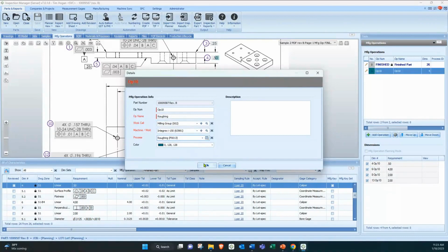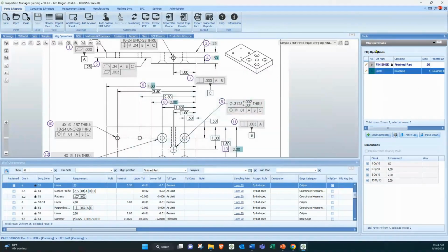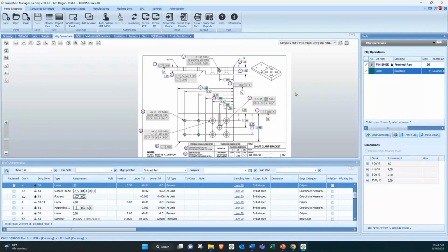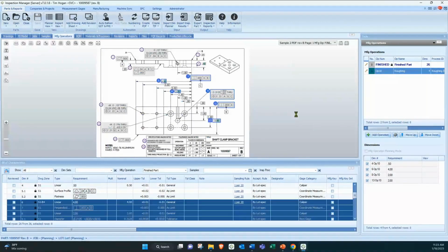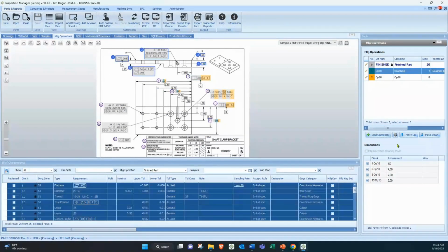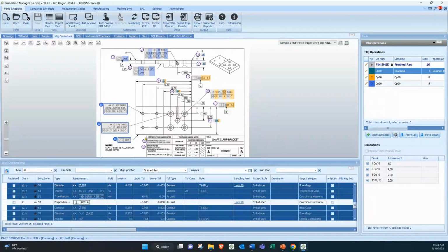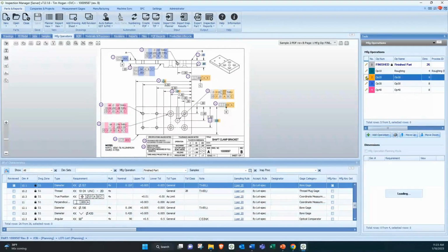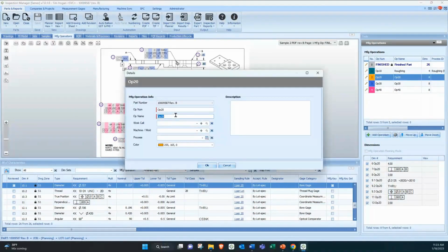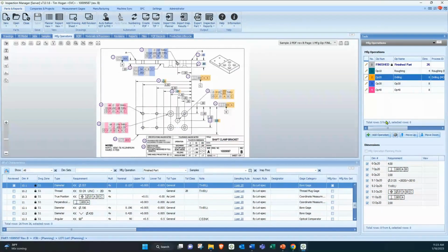So as we identify the process here, now we have our roughing operation and a roughing process as well. I'm going to add a few more here, so pardon me taking a couple minutes, but you can box select them like I'm doing. You can individually select them however you want. It's really up to you. So we're just going to add those 4, and I'm going to go in and manually, let's call this a drilling operation. We'll tie this to a drilling process. Say okay.